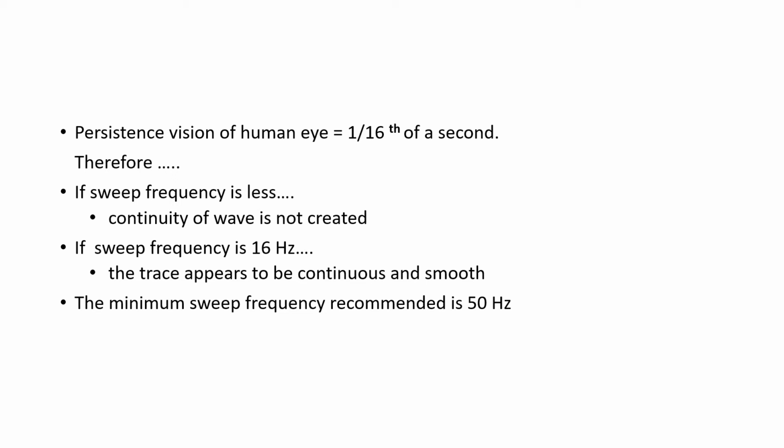To sum up, the waveform observed in a CRO must be free from flicker. In order to get a flicker-free waveform, the sweep frequency generated by the horizontal sweep generator must be greater than the persistence of vision frequency of 16 Hz. It is better to have a sweep frequency greater than 25 Hz. Flickering is due to measurement of low frequency signals, and the free running mode of the sweep generator is not suited to the vertical input signal.